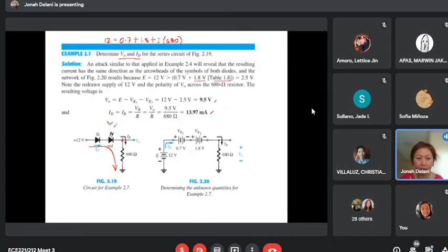Notice from this example that for the LED, the value is different. In this particular example, the red LED has 1.8 volts across it if it is forward biased. It is not the same for all colors. So the threshold voltage, or forward voltage, is different for the LED. For different colors, different forward voltage values. In the illustration, 1.8.